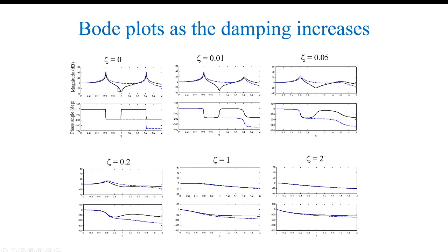What does it mean to have negative infinite decibels? Negative infinite decibels divided by 20 is still negative infinity, and 10 to the negative infinity is what number? I'm trying to change this number, say negative 40 decibels or a very large negative decibel value, into a pure ratio. So you have 10 to the negative infinity, and that's definitely not infinity or negative infinity, that's 0, nearly 0.